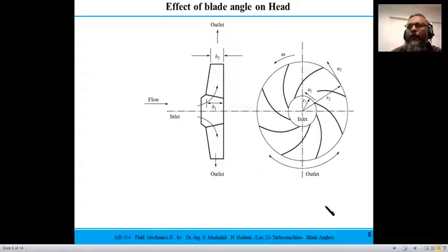We see this impeller, and the performance parameter comes from the Euler equation of turbomachine, which is the magnitude of the power either given to the fluid or extracted from the fluid, depending upon the difference of the product of the blade velocity times the tangential velocity at the exit and at the inlet. So if the velocity at the exit is much bigger, it means the blade has actually imparted energy, so the velocity at the exit is much greater than the velocity at the inlet.